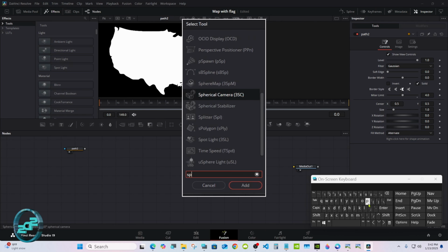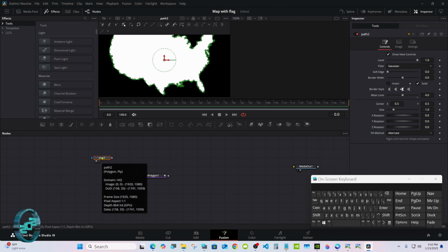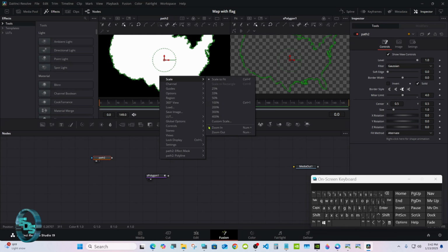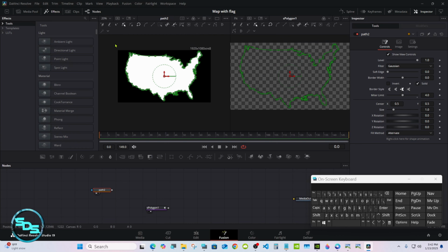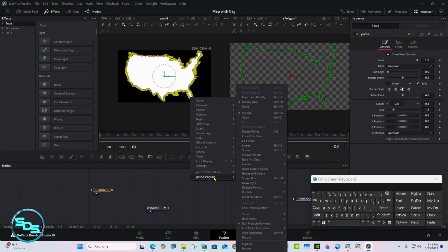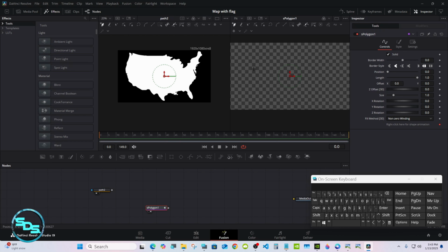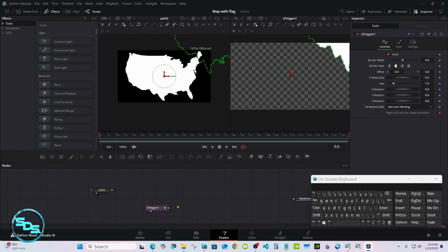Okay, click away right about here. Shift space and S polygon. We have to transfer all the data from the SVG file to the S polygon. Put the S polygon in viewer 2, with the SVG selected. I'm going to highlight all these points. Right click on any one of them, down to the bottom, copy. Select the S polygon node. Go to viewer 2, right click, down to the bottom and paste.